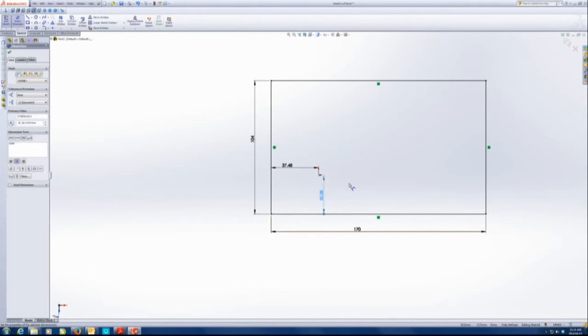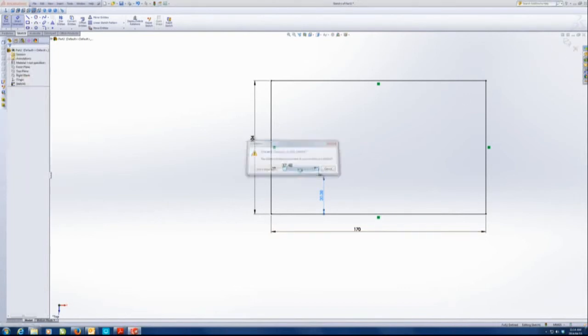So basically, every sketch you draw wants to have a friend, wants to be related back to the origin, and that's what we do here. If you don't start drawing on the origin, you need to at least put your dimensions back to one of the edges, both in the X and the Y axis. Okay, good. That's exercise 1.1.